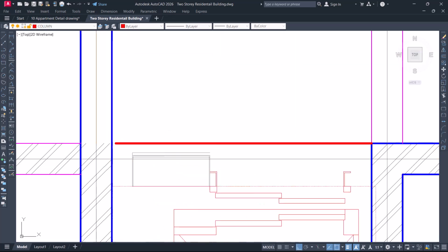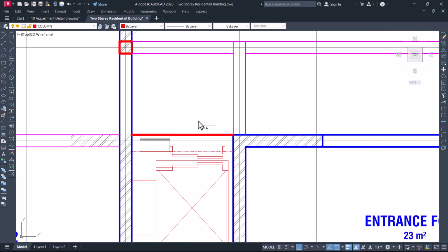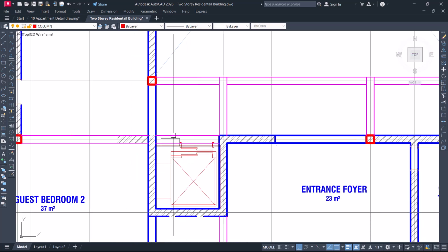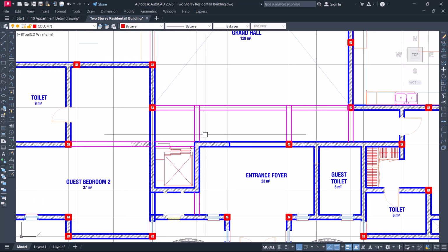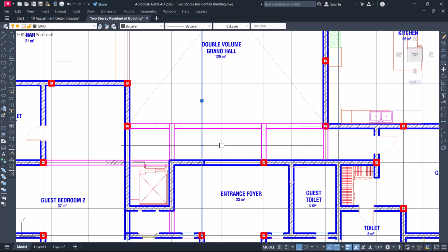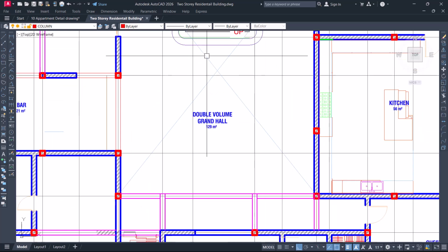Then extend. All right. Then also offset downward. Then match it now. Here I'll match this to this. Correct. But this is a reinforced wall. Don't forget that. It's a reinforced wall binding here together. Okay, that's fine. So right now we now have this panel, this panel, this panel. Okay, and then all here to be void.